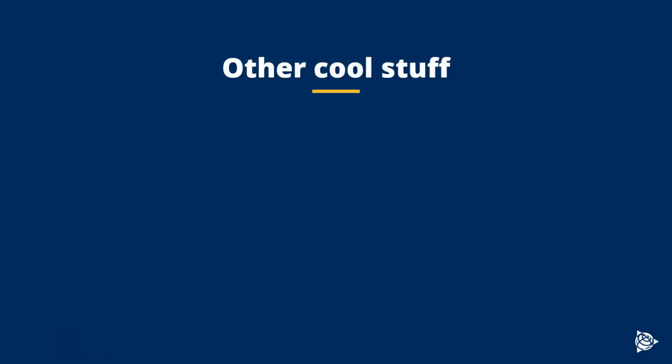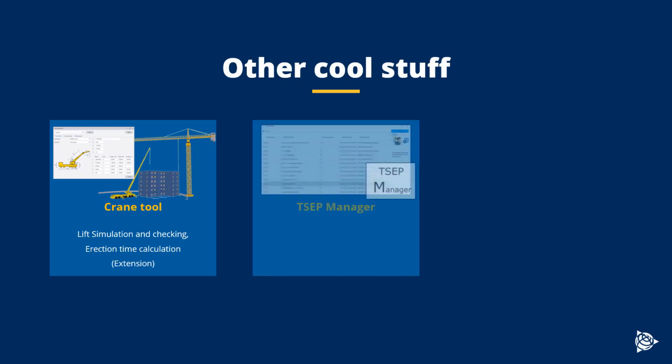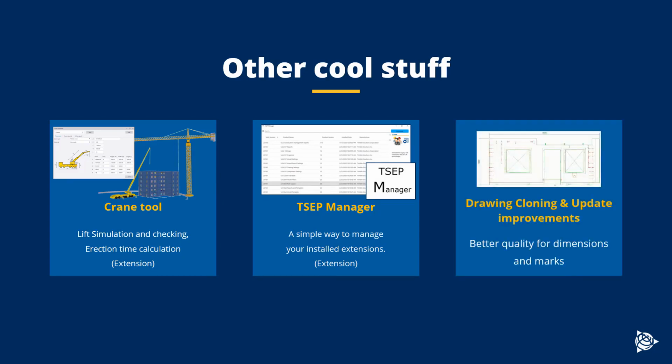Of course, that's not all there is. There's a bunch of other great tools, such as the crane tool, which is great for lift simulation and checking erection time calculation. As an extension in Tekla Warehouse, we have a TSAP manager, which is a simple tool to manage all the extensions that you have installed, or many other improvements in the core side for cloning and updating the drawings, and that's really improving the quality for dimensions and the marks. And of course, there is much more.